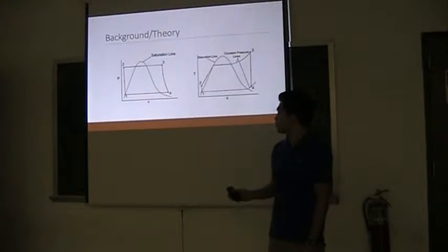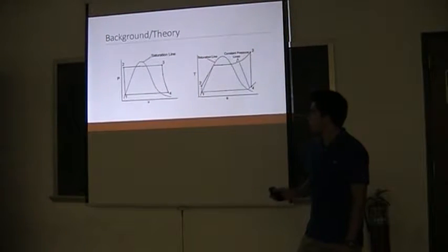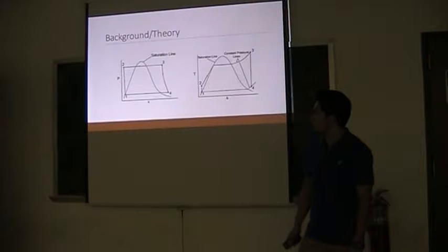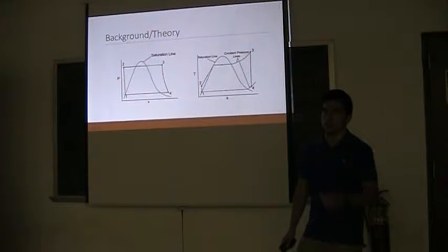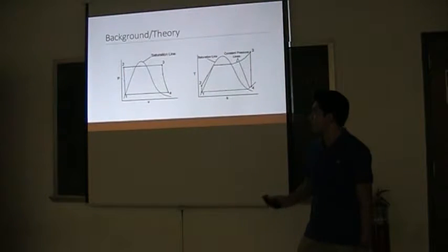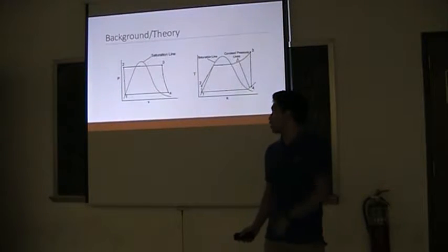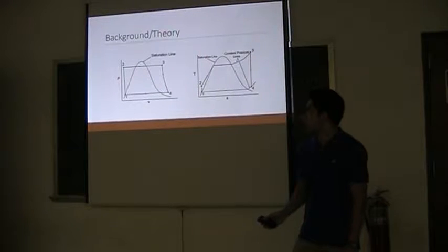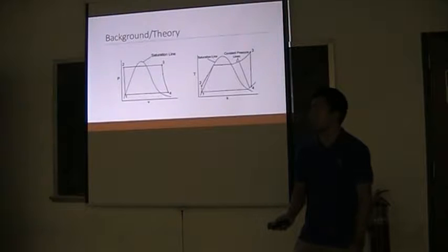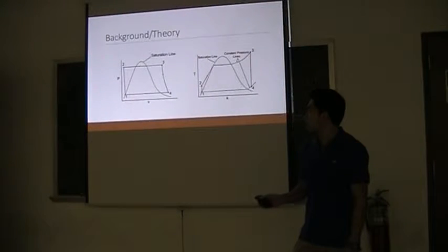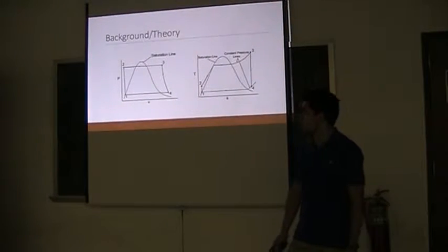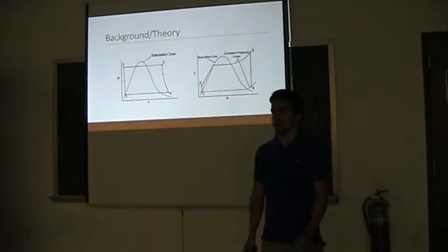All right. So to continue, on a PV diagram, from points 1 to 2, which is from the pump going into the boiler, it increases the pressure. Then from 2 to 3, it stays at constant pressure, and it actually increases the temperature. And then from 3 to 4, it's a decreasing pressure after the work is being done by the liquid on the turbine. And then from 4 to 1, it stays at constant pressure again when it goes through the condenser